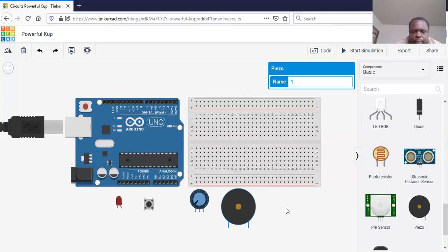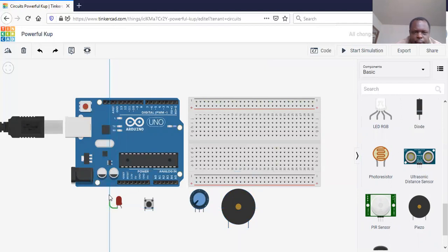But if you want them to do specific functions, then you need to connect them correctly. If you want to do a wire, in most cases, you can just pick the wire. Like now, if I want the cathode, I connect it here. So you click on the device terminal, then if this is my ground, I just put it there.